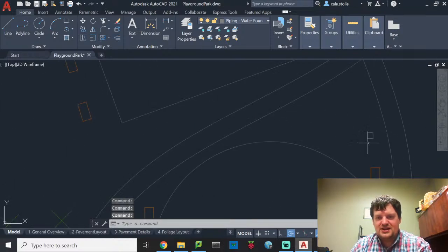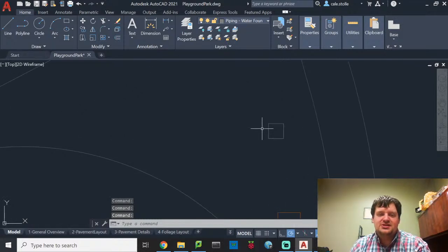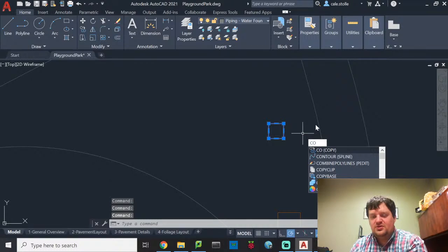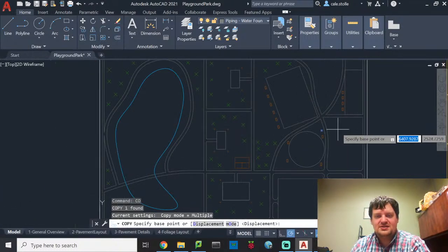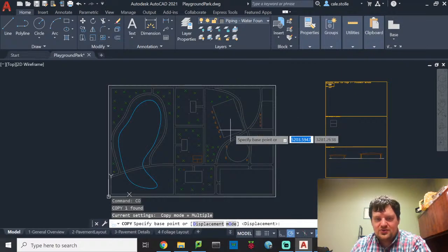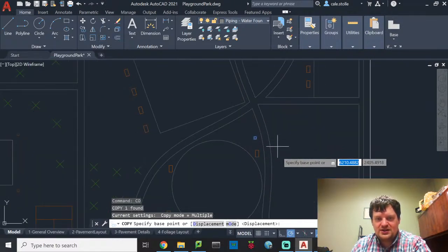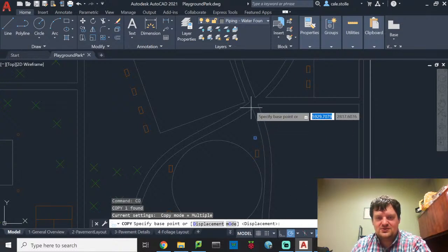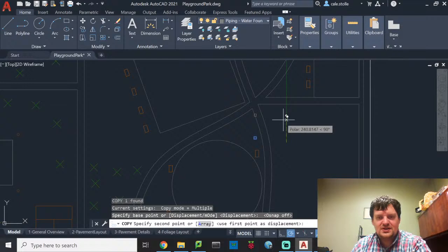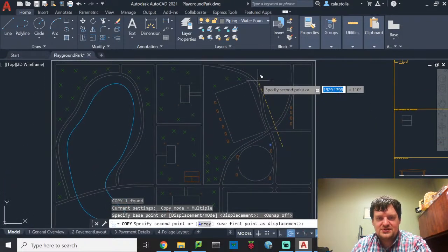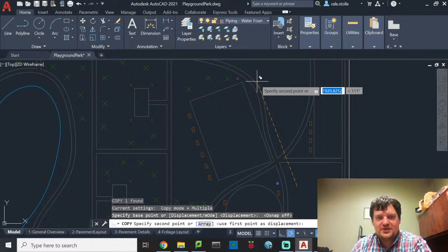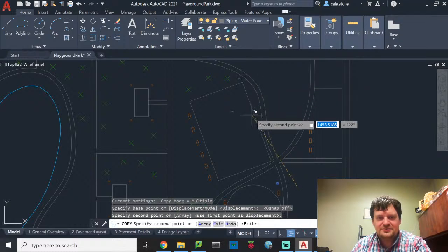And I'm not even going to rotate it. In an actual drawing, you'd want to rotate it just so it looks clean. I'm not going to because it's just going to take up time, and all of you who are watching this video, you're already spending time watching it. Okay, now I'm going to copy and paste this, and when I do, I do not want to have OSnap turned on. Object snap is where I see this corner right here. My cursor wants to go to that point. I'm going to turn off object snap so that I can just click and drag and position this as I will. We'll put another drinking fountain on this walking path over here.